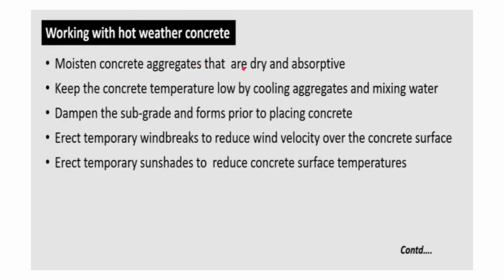So, working with hot weather concrete. How do we now find mechanisms which can overcome all those problems and give us some sustainable solutions? Moisten concrete aggregates that are dry and absorptive. We have to keep the concrete temperature low by cooling aggregates and mixing water.